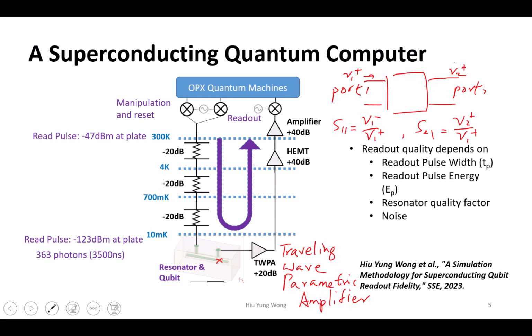Now, some of this we are not discussing here. Maybe I may discuss a little bit in a future lecture, but we discussed it in E226 already. In an amplification chain, you want to have the lowest noise figure at the beginning, right? You would rather have a small amplification but add less noise, because any noise you add is going to be amplified later. So you want to add less at the beginning.